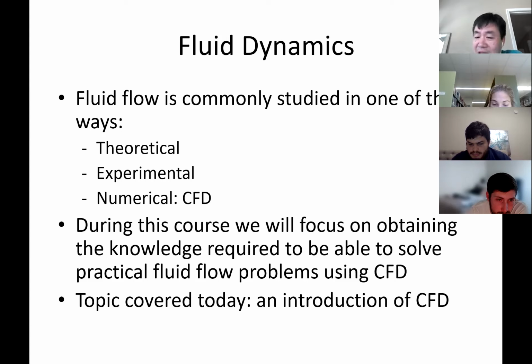You can't. They still have to do small scale, but they have to adjust something to make the Reynolds number the same. You know Reynolds number? You had my fluids class, you should know the Reynolds number, right? Think about it: the Reynolds number is the size times what? Velocity divided by viscosity, right? Or density times the size times velocity divided by the viscosity. So if you want to use a small scale to ensure the same validity, you have to make sure the Reynolds number is the same.